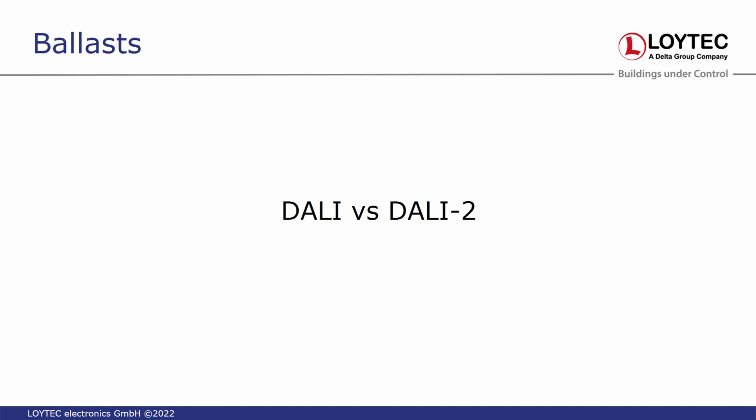Yes. Actually, maybe I did understand you wrong. For the L-DALI, it doesn't matter. The L-DALI works with DALI 1 and DALI 2 ballasts the same way. So this is not a problem. Special handling for the standards only comes in when you talk about occupancy sensors and other kinds of sensors. This was not standardized in DALI 1, but regarding ballasts for the L-DALI, it doesn't matter.